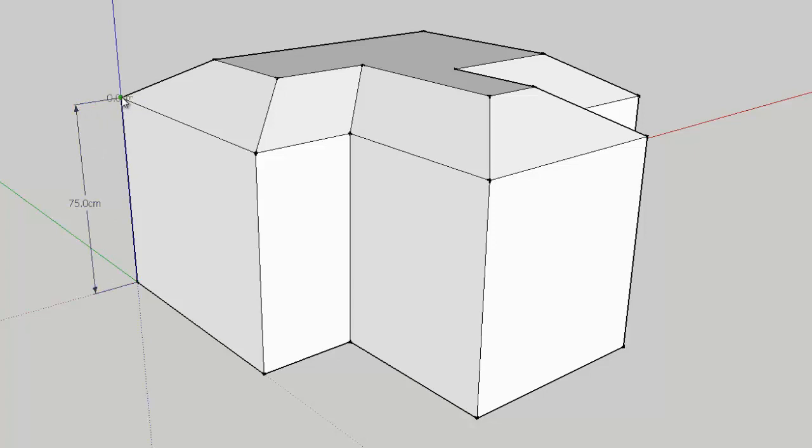Click on the chamfered edge at the top here, go to the other corner, click and pull that out, click, gives you the height. The height of the chamfer is 15 centimeters. Let's put another dimension in, the dimension from here to there, and always pull it away from the object. Here over to this corner. You don't need to do the height again, it's the same on all the other corners. That is one view of the object.